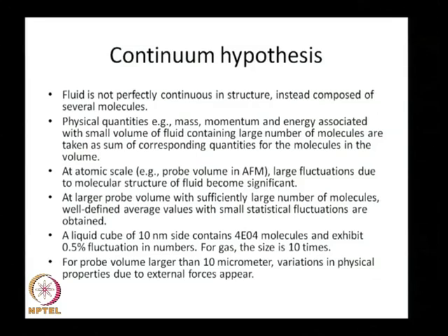What the continuum hypothesis says in this regard, let me put together. Physical quantities such as mass, momentum and energy associated with a small volume of fluid containing a large number of molecules are taken as the sum of corresponding quantities for the molecules in the volume. What that means is, you take a volume around which you would like to know the mass, the momentum and the energy associated with that volume.